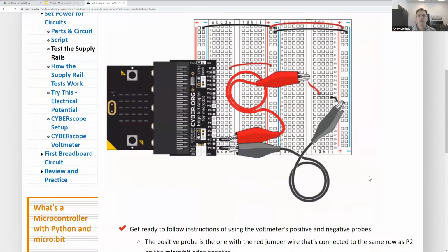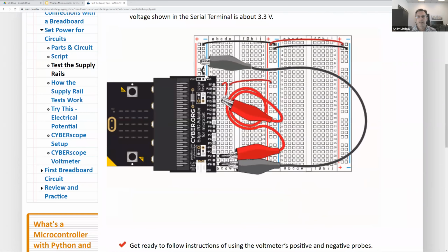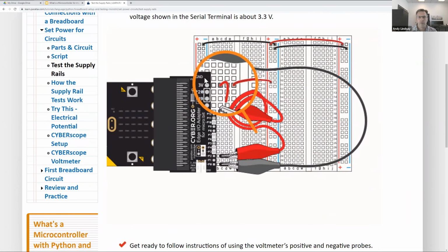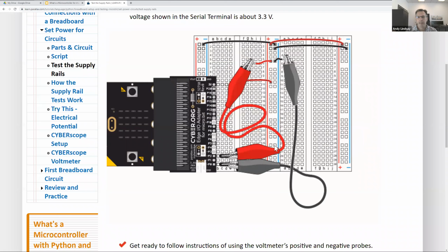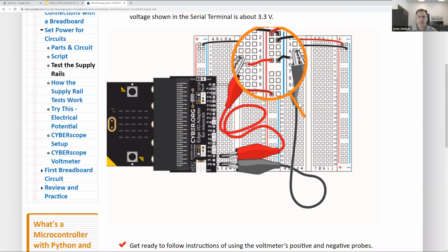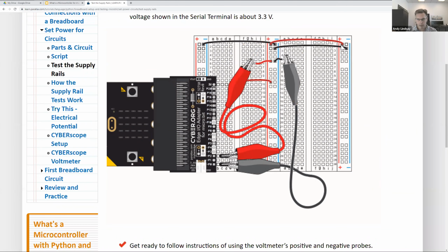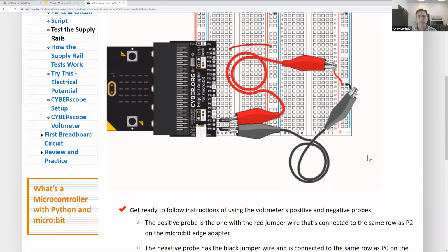But just so you know, there is a step where you go through with the voltage probes and measure voltage, making sure that everything in the blue stripe sockets measures as 0 volts, and everything in the red stripe sockets measures around 3.3 volts.